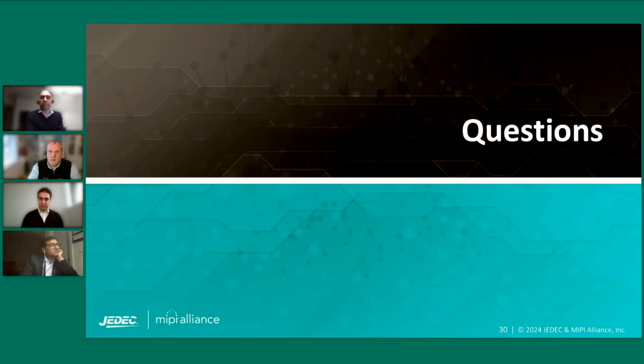Next one: does UFS allow use of other transport layer, link layer, SerDes combinations other than UniPro and M-PHY? Theoretically, yes. It is built in a layered mode, so UFS is agnostic, let's say 99%, to what's below the application layer. De facto, we are going on with UniPro and M-PHY.